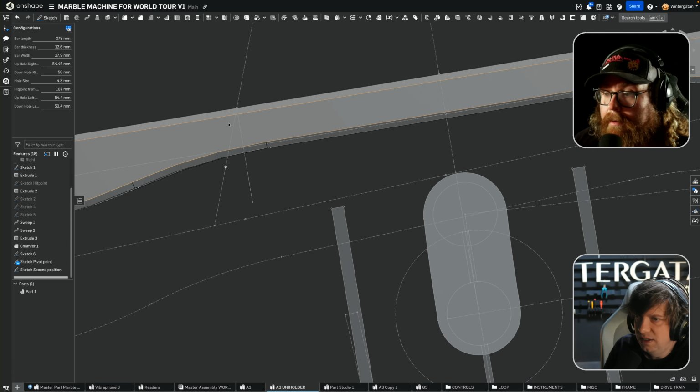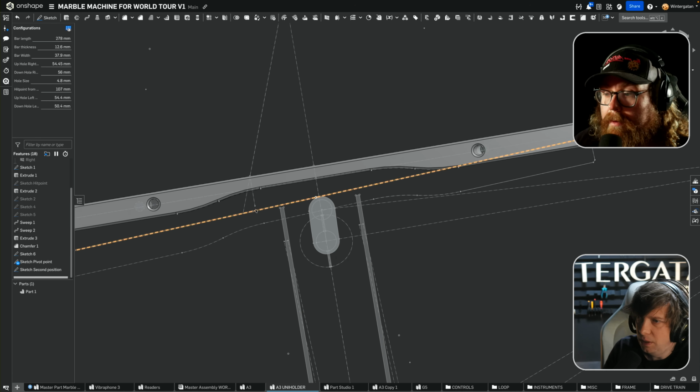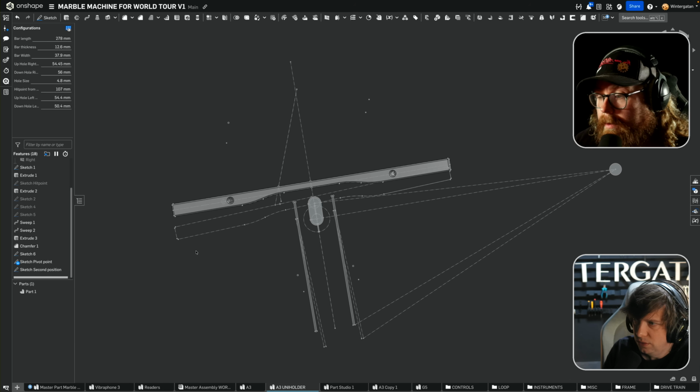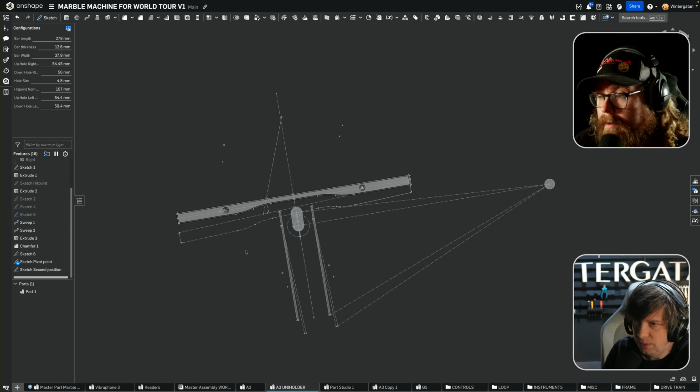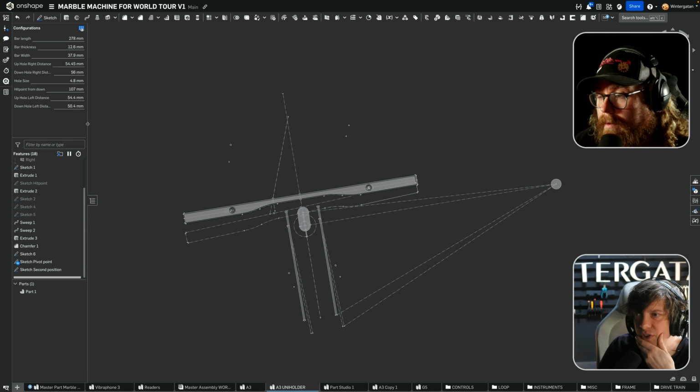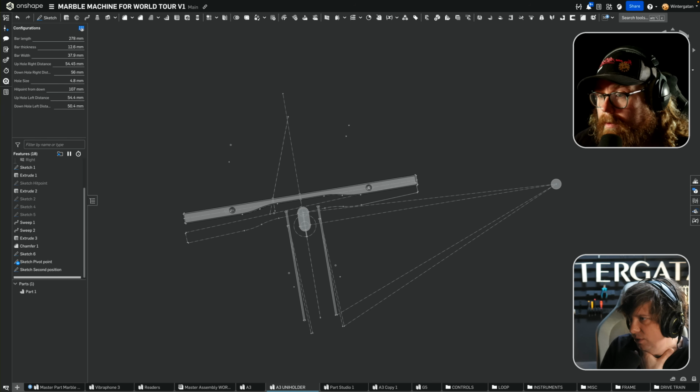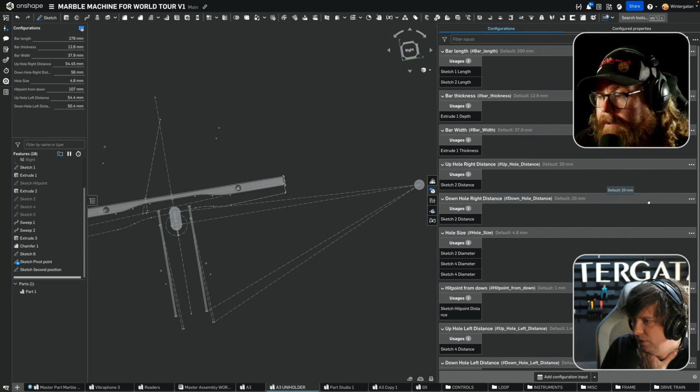I can actually see here that the plate moves more than 15 millimeter. I think that's too much. So what do we do to change that? I think we're gonna reduce the degrees of our circular patterns. And I think we should add that to our variable in the configurations, because I have that value in both sketches and I shouldn't do that manually. I want to control that from a central point.